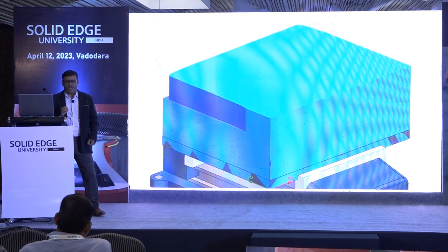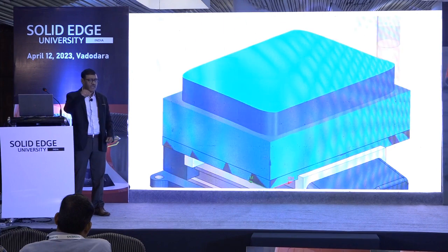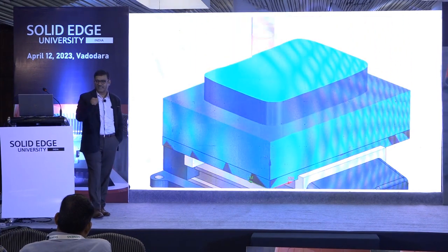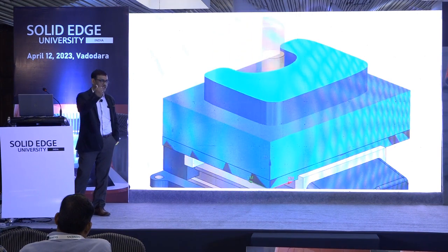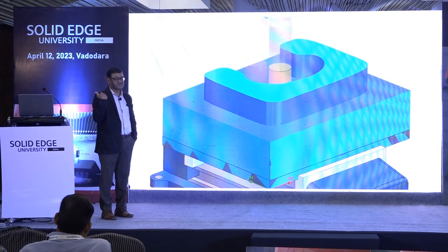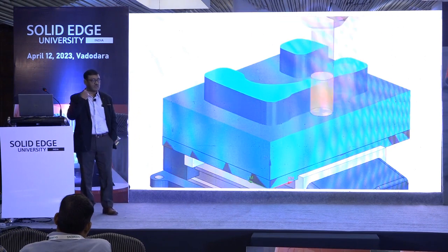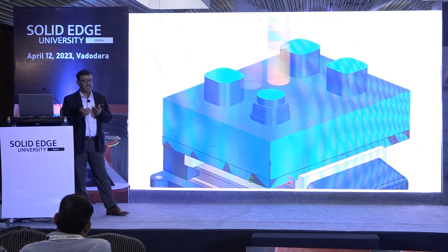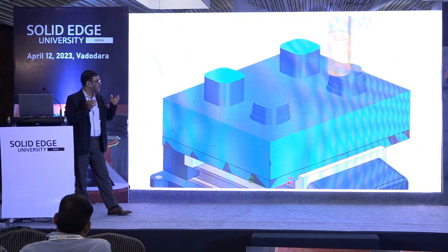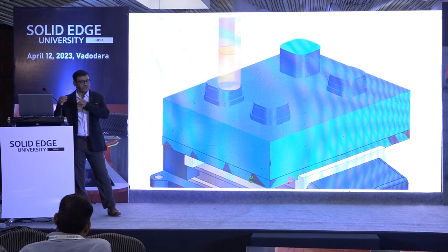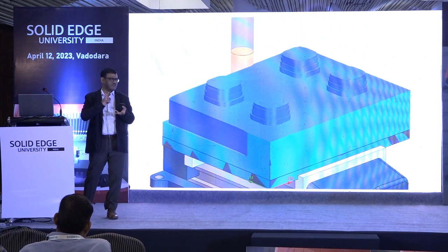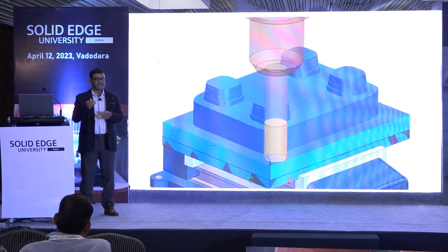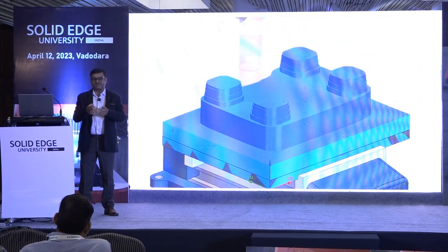Apart from this, normally we have a habit of just seeing the IPW, the in-process workpiece, right? So you can generate the toolpath and see it before cutting. Because in this process, it looks simple, but if any collisions are there, you digitally validate your toolpath. That's our recommendation: shift left. Normally, if you do anything on the shop floor, you waste operator time, machine time, and cycle time. So it is always recommended that any validation you want to do, you do in a digital way. That's our recommendation.